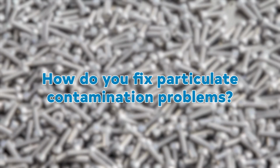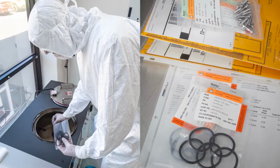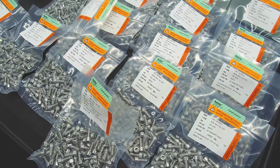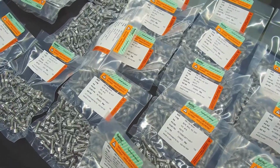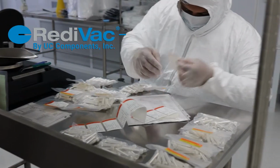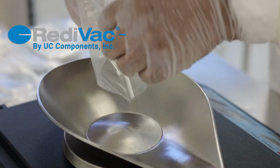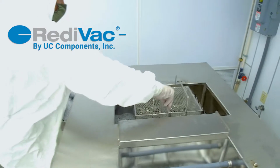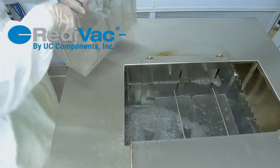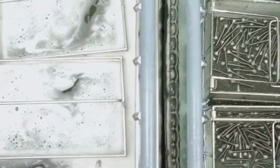How do you fix particulate contamination problems? Properly cleaned and baked O-rings and vented fasteners, such as the ReadyVac line from UC Components Incorporated, is your best option. The ReadyVac branding signifies an added level of particulate cleanliness assurance via in-process inspection, post-machining deburring and rinsing, followed by multi-stage ultrasonic cleaning in a controlled environment.